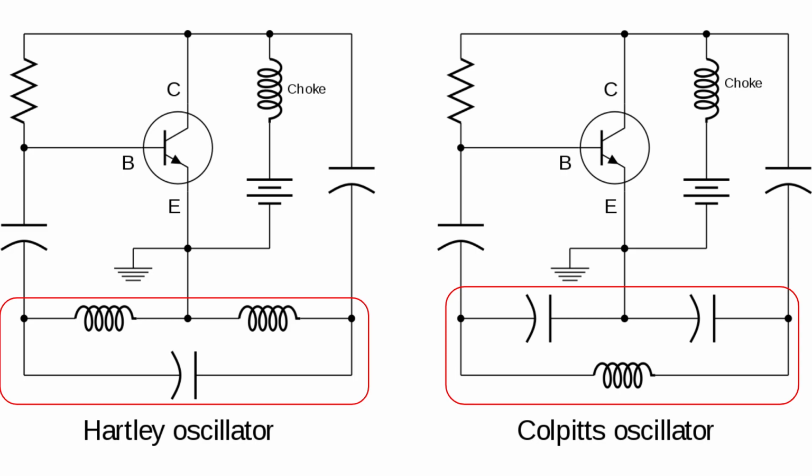Okay, so in these two circuits, as you see, there is a variable capacitor here, right? So you can adjust the oscillating frequency. This is what a quartz crystal cannot do. Okay, it has some room for change. But I remember that the Hartley oscillator, because it uses inductors more, can withstand a higher frequency. But the Colpitts oscillator can do more fine-tuned, more precise stuff. These two circuits can be used to replace quartz if your circuit needs to withstand a lot of energy and you need to change your frequency from time to time.